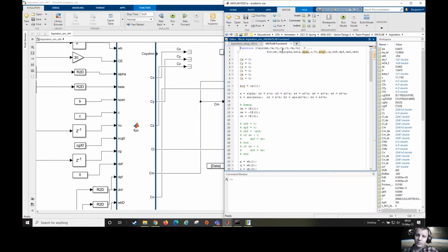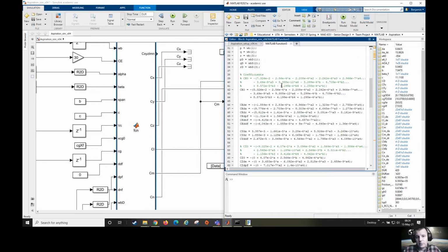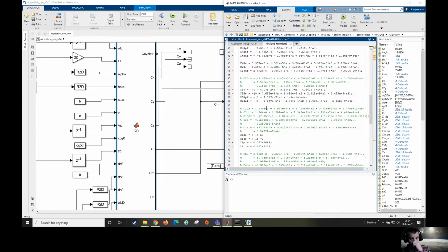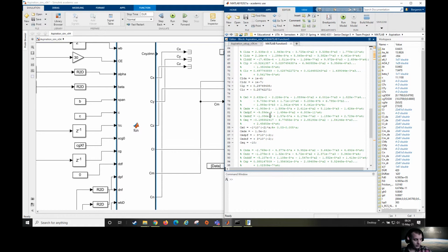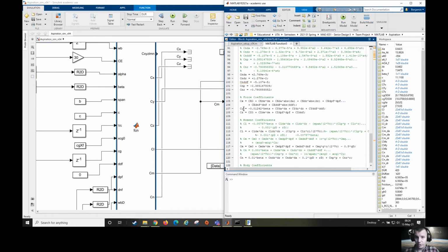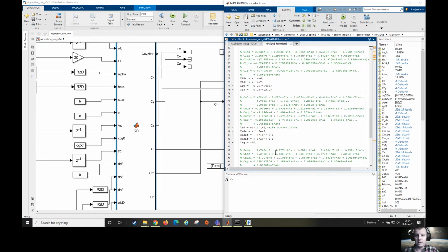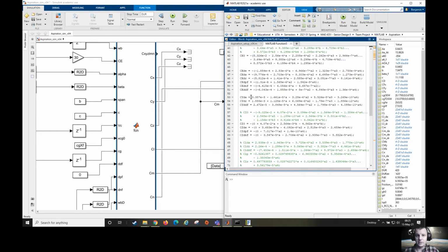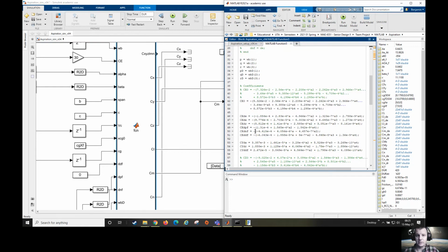It's a modified HL20 subsonic aerodynamic model. It goes through and calculates everything based off of alpha and beta. I had to modify a few things to make it controllable, in particular for CL, CM, and CN. Everything else, CX, CY, CZ, is as initially designed.